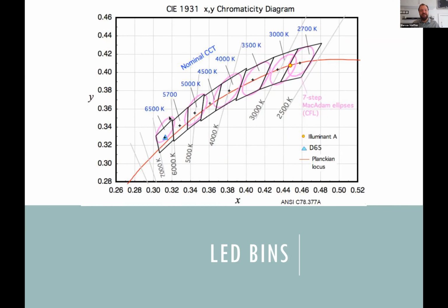And our eyes can tell the difference between all of those. So buying one LED which says it's 2700 and another LED which says it's 2700 is not going to result in matching LEDs. And so manufacturers, or some manufacturers, have taken this further and specifying we do ours to a 4-step or a 3-step or a 2-step MacAdam's ellipse matching to show that they're doing accurate binning.